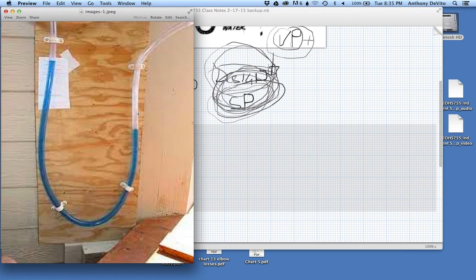So it's pushing air. The air is pushing the water down, and if this side were just exposed to the atmosphere, it would allow it to rise, and the difference in height of these two is the number of inches of positive static pressure we have downstream of the fan. Keep in mind that typically, the way we would use this as a simple manometer would be one side or the other would be open to the atmosphere.